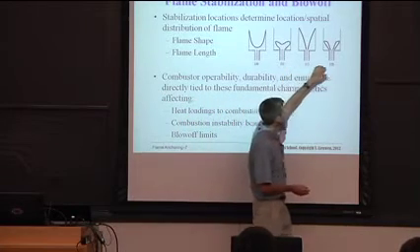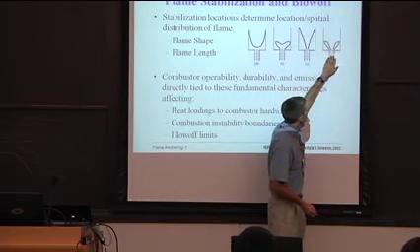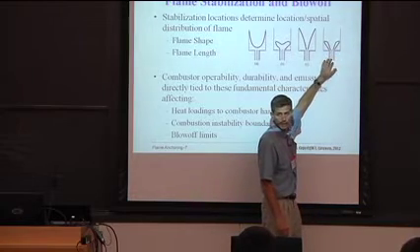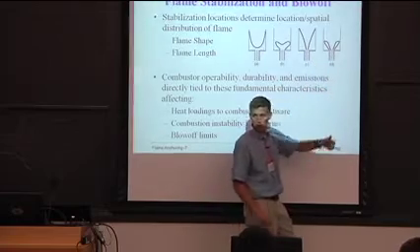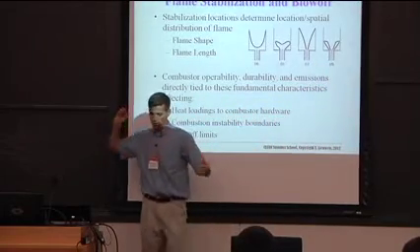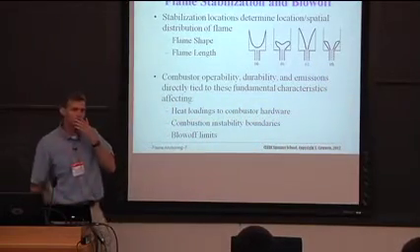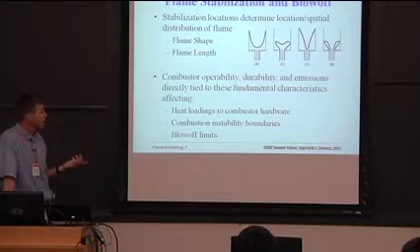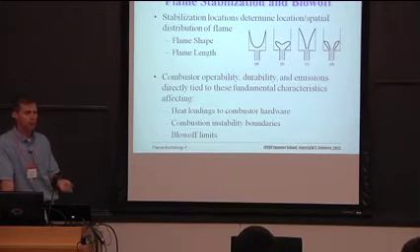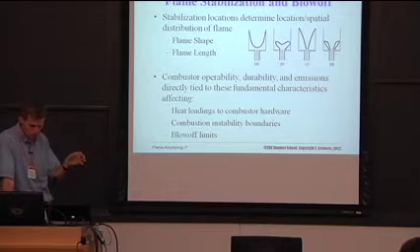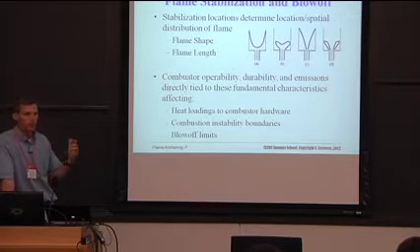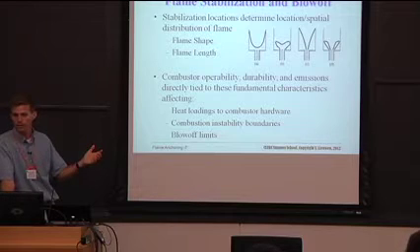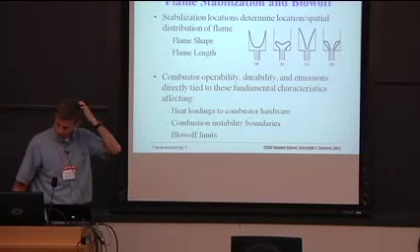So if your flame is sitting in the inner and outer shear layer here, it can consume the fuel and basically half the flame length is just sitting in the inner shear layer. So you can get this very abrupt bifurcation where the flame length just goes pop, it changes by a factor of 2, and if that happens to move you into a region where you have instability, all of a sudden you'll be creeping along, making a small change, and all of a sudden, bang, the thing might start oscillating like crazy. By the way, this happens.